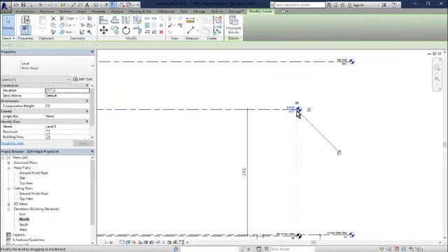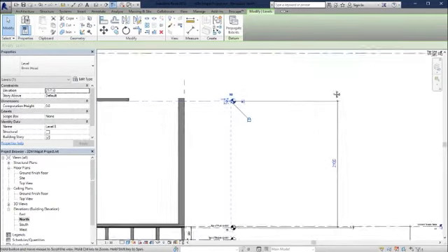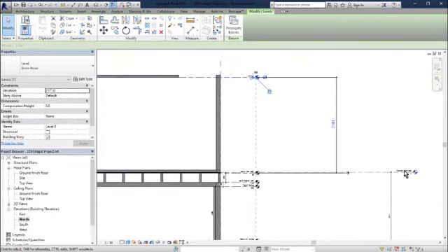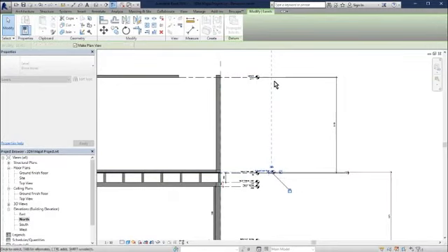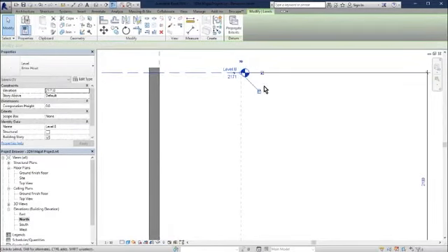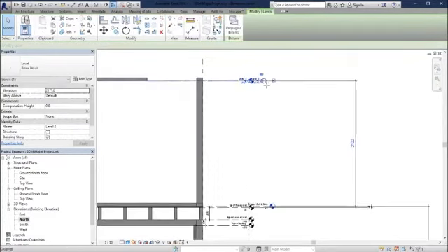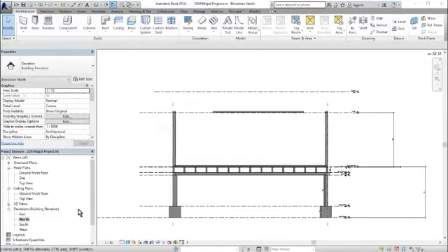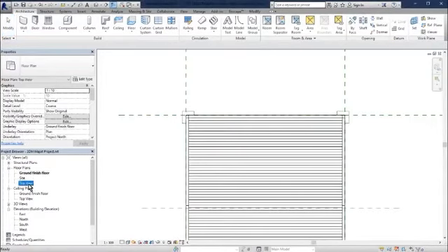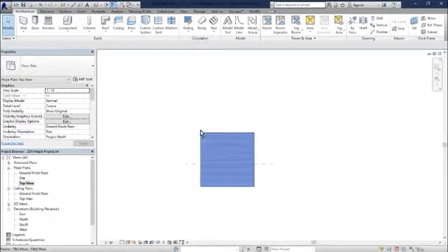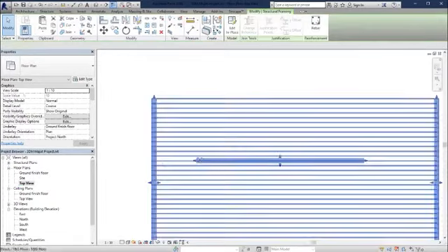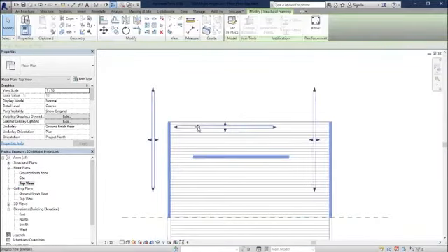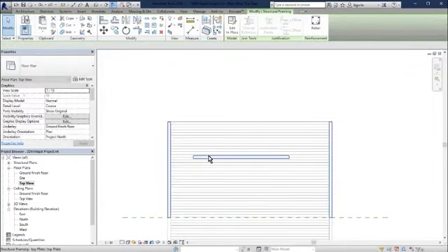Carry these levels into there, and I'm going to carry these levels over like that, and carry this level like that, and let us make this level align with that one. Okay, so now if we go back, and instead of going to our ground floor, we're going to go to top view. And now that we go to top view, we can actually see our wall plates.